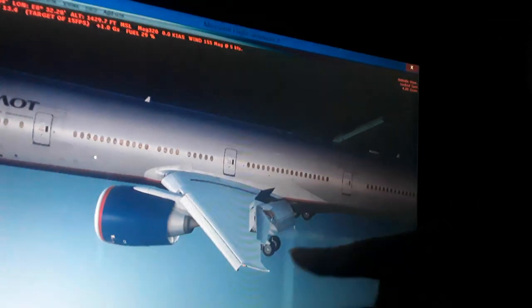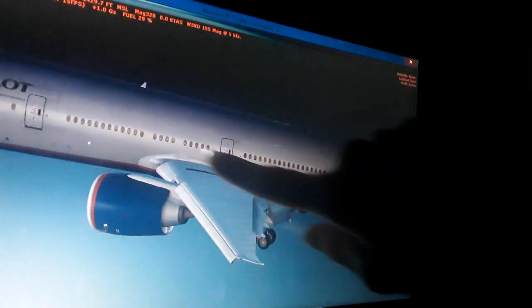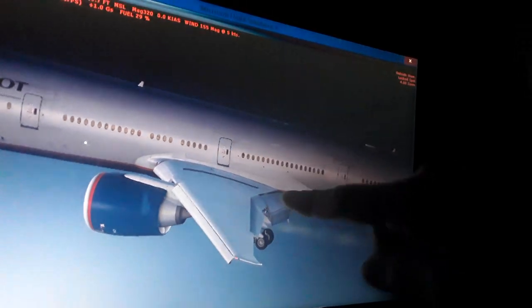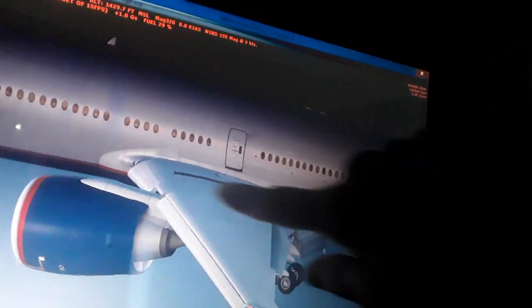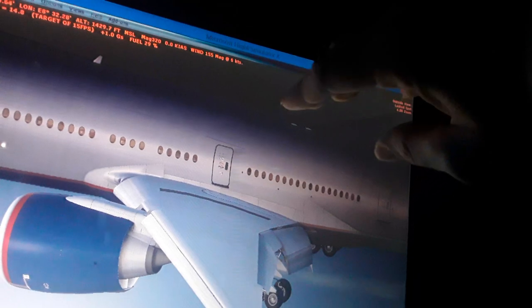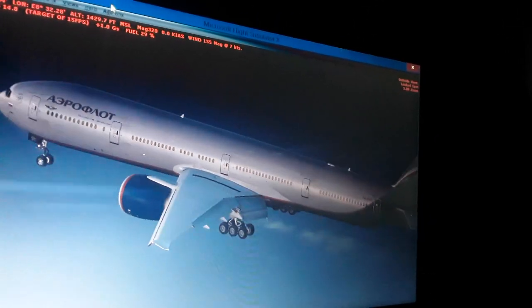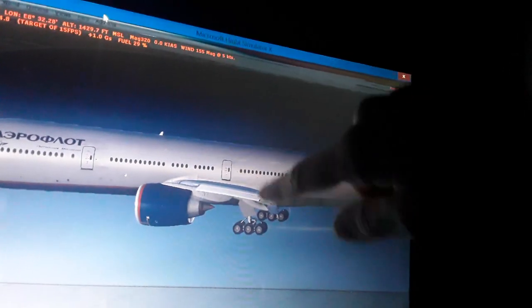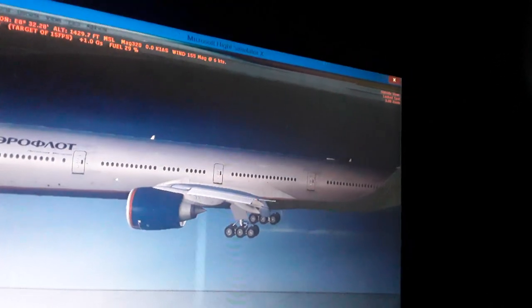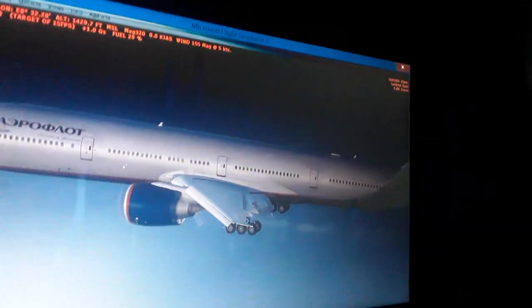Also the top surface of the wings is more curved. So you can see the airflow of the air mass as the aircraft accelerates to the takeoff speed is moving faster above the wings, so we have lower air pressure above the wings. This creates an air suction above the wings, which sucks the aircraft up into the air. So you have negative air pressure above the wings. So you have more pressure that pushes the aircraft up into the air and less pressure above the wing. So this is the differential pressure between the bottom and the top surface of the wings.